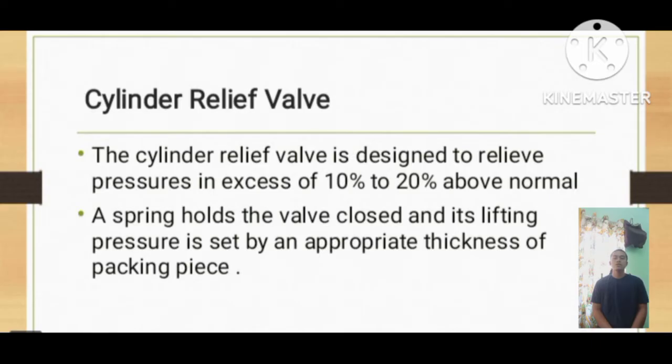In most cases, dirt accumulated on the seat can be driven off this way. A gentle knock on the spindle can also help stop the leak. Number three is to inform the bridge about the issue and ask them to reduce stop-starts.